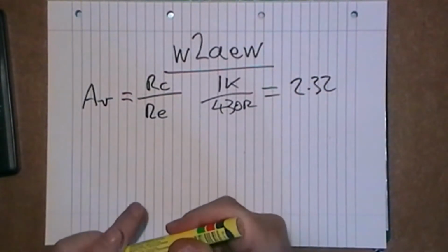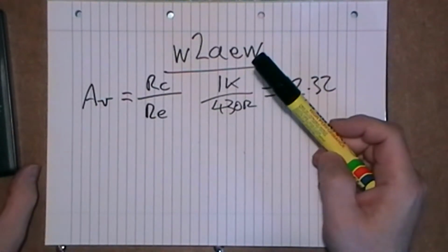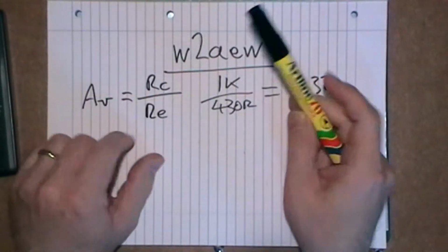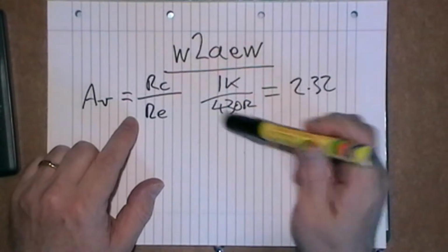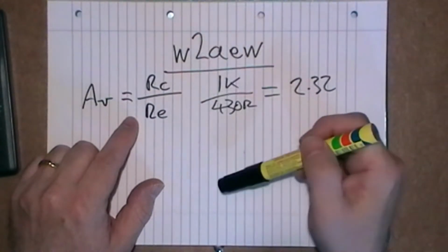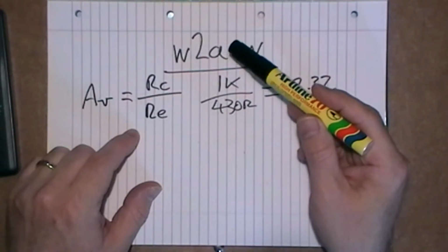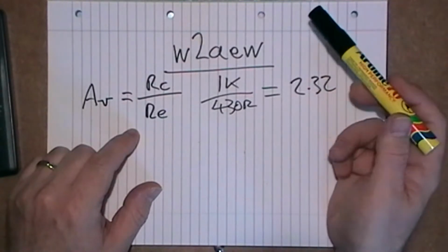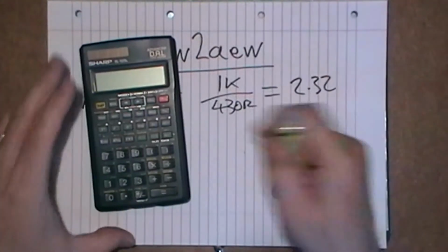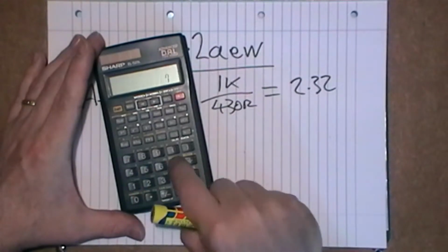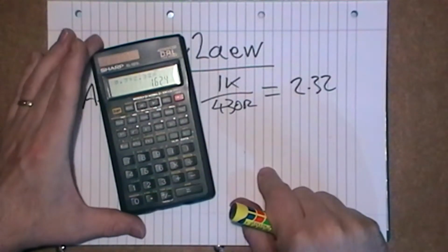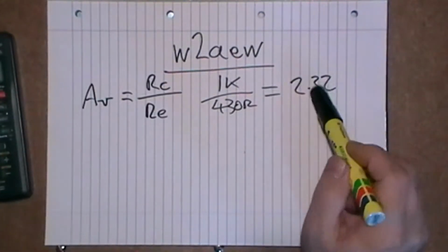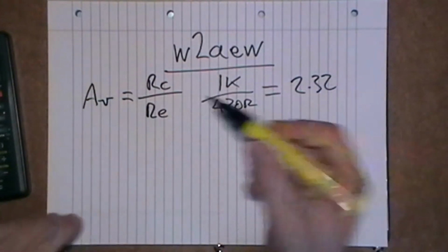I don't know, because obviously on the base, it only needs 0.7 of a volt to turn on the junction, regardless of what I put across there, even though I put 2 volts on there. But what's that? 0.7 times 2.32 gives me 1.6, and I've actually not got that at all, so I'm not quite sure what that means.